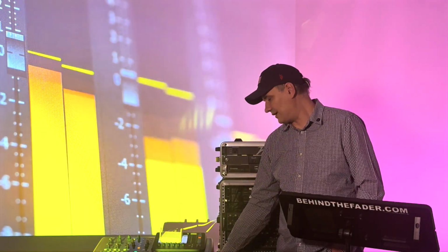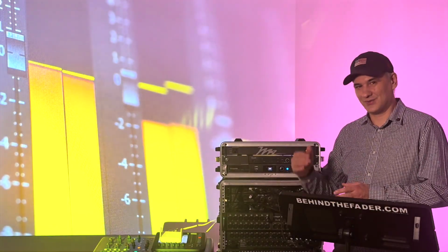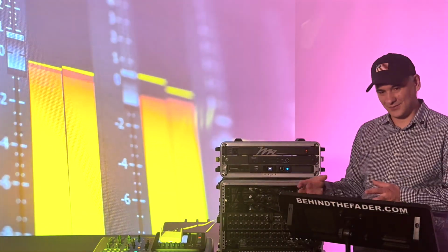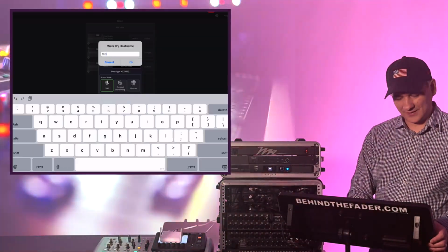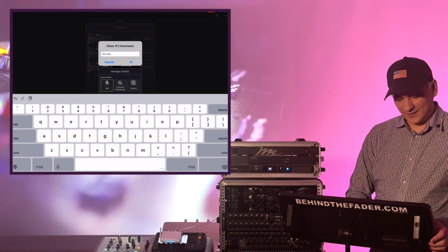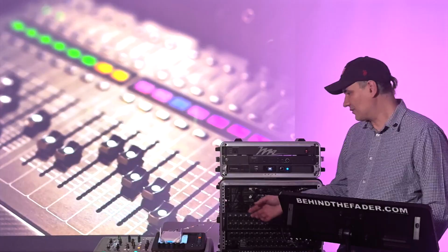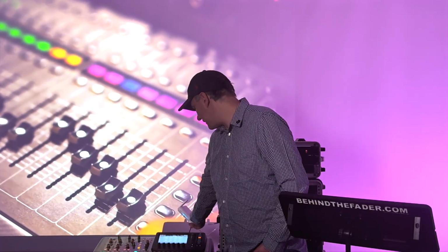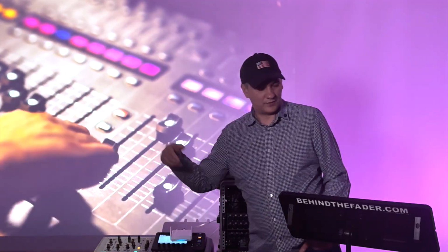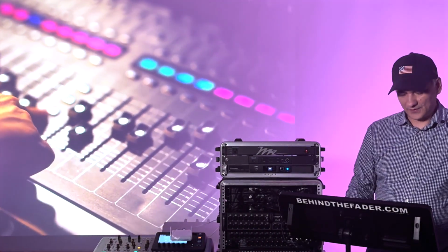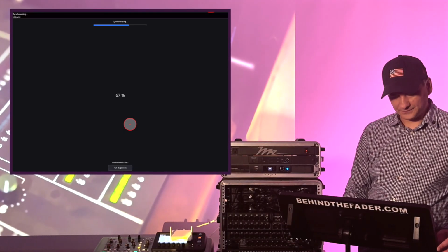So we need the address of this guy, and you should have your notes, right? Remember, I told you to write down all your information that we just collected during this video. So the IP address of this mixer is 192.168.8.11. If for some reason you didn't write it down, or if you forgot the IP address, you always can go to setup, network, and it will show you the IP address. So, okay, let's try to connect to this Behringer X32 now.